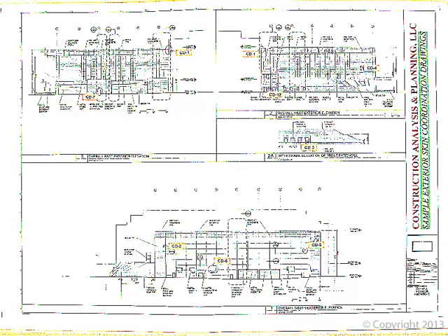At the bottom elevation, you'll see CD2 represents the vertical joint between precast and brick, whereas CD3 represents the horizontal joint. CD4 in the top right appears to be just a cut through the middle of brick, but this is actually a brick ledger angle. Brick needs to be supported intermittently up the face of a building, which is traditionally done with a steel ledger. Now we'll go over an example of one of these in part 2 of this course, but coordinating the face of brick, steel ledger, secondary membrane behind the brick, and flashing that occurs here can actually be very difficult. CD12 in the top right represents a somewhat awkward condition at the storefront.